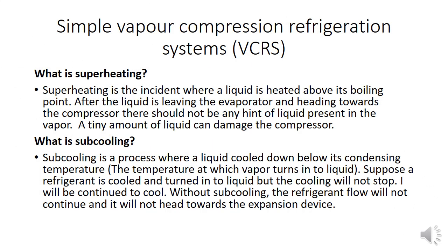This simple vapor compression cycle generally consists of two additional features. One is superheating, another one is subcooling. So what is superheating and what is subcooling? Superheating is the incident where the liquid is heated above its boiling point.